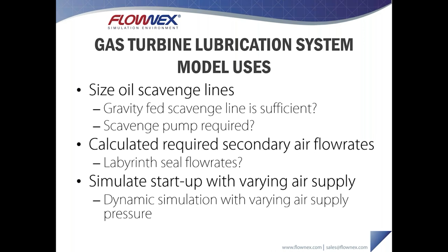Another application would be in analyzing the air side. These bearing chambers are sealed by air around the shaft itself. In that case, it's important to know the secondary air consumption for the purpose of designing secondary air systems. So working out what that secondary air flow rate will be would be a good application.